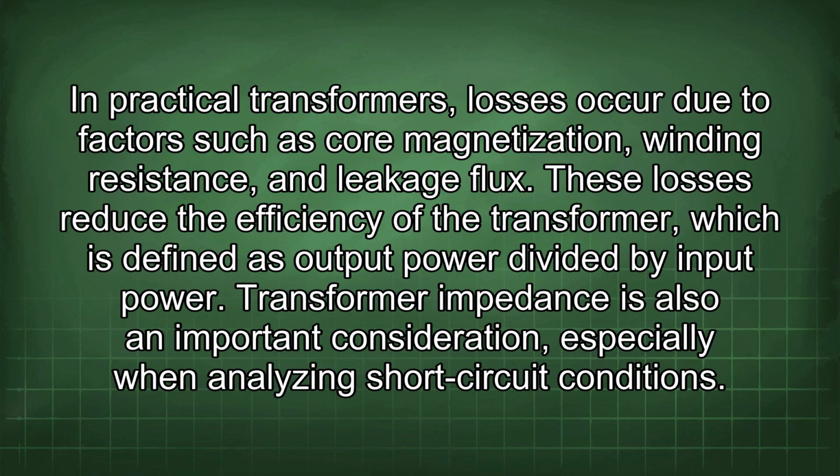In practical transformers, losses occur due to factors such as core magnetization, winding resistance, and leakage flux. These losses reduce the efficiency of the transformer, which is defined as output power divided by input power.